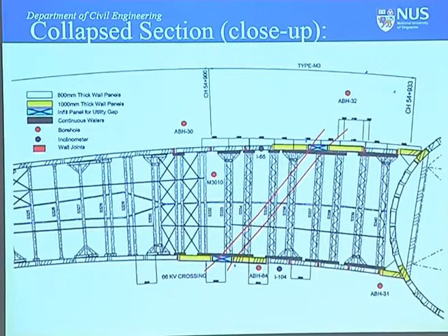The second thing that I'd like to draw your attention to is these things. You see, these are the bracings, the struts, right? But there's no continuous waler going across. These are very short walers, short lengths that join the struts to the wall. And the panels are not joined one-to-one. It's a very, very haphazard kind of construction.